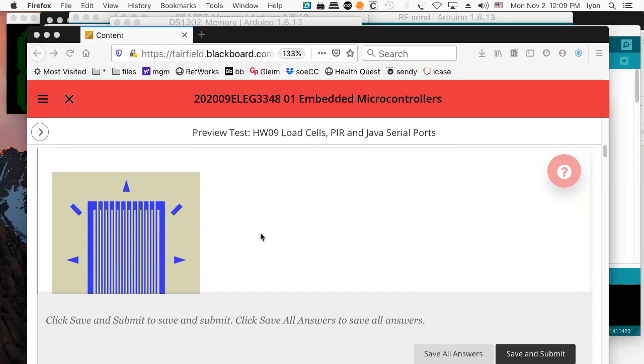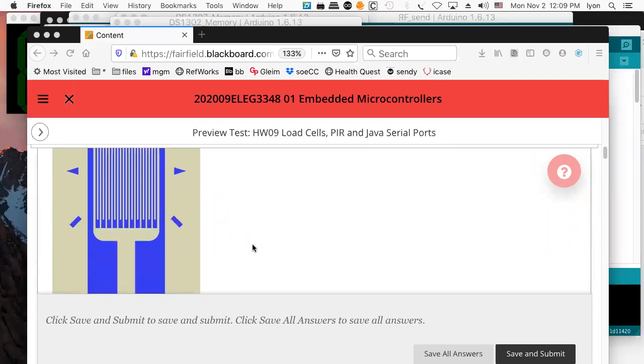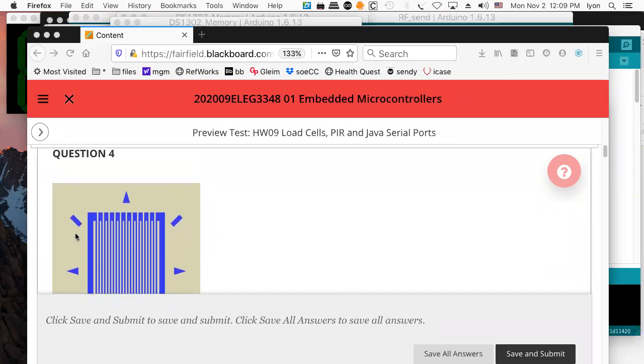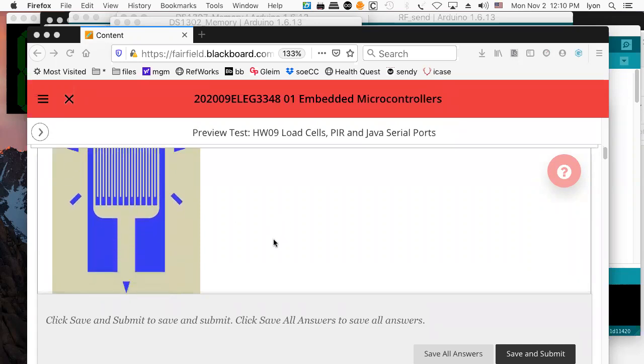And when you're designing a printed circuit board, you want to avoid sharp corners in your printed circuit board traces, because each one is going to work like a little radiator, like a tiny antenna. So if you're designing antennas, the sharp corners might be good if you're doing a microstrip antenna. But if what you're trying to do is design a circuit board where the electricity flows smoothly like water, you don't really want to have sharp corners. Oddly enough, currents don't like going around corners.